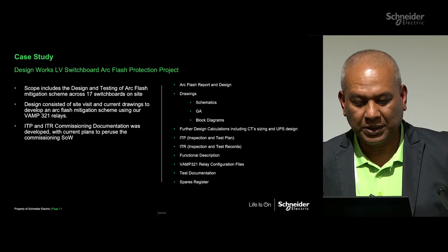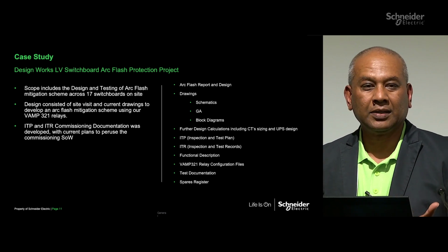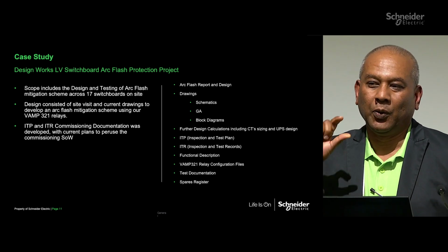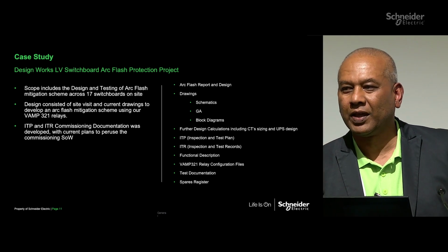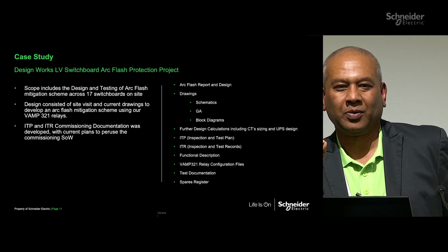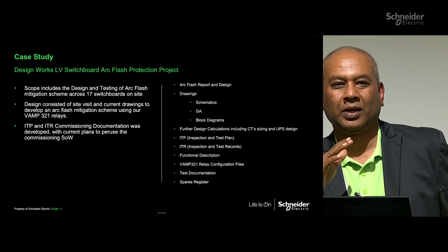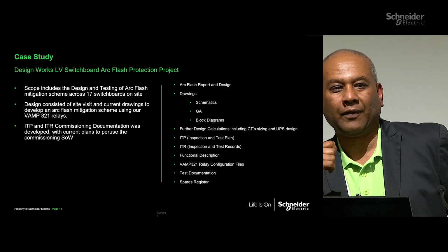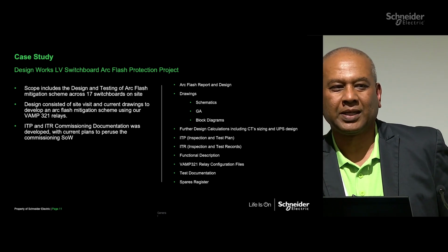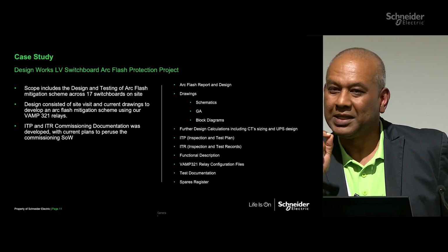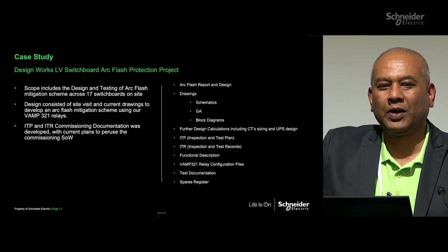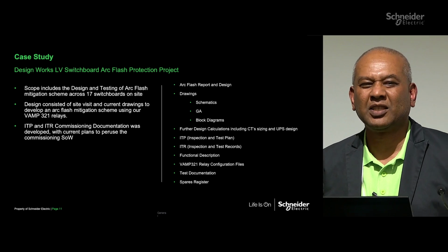The customer was a bit conservative. These days, with modern technology, we actually detect the signature of the arc. The arc has a very unique signature in terms of the light, so the relays are able to detect this. Ambient light, a flash from your cell phone or a camera, none of those trigger that detector. It needs to be a precise arc flash, which has its own signature in terms of waveform. So there is no nuisance tripping.